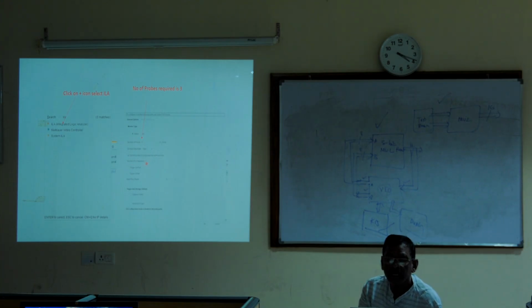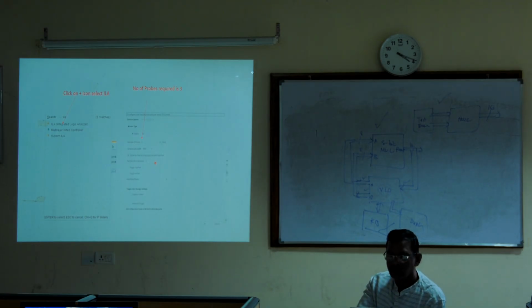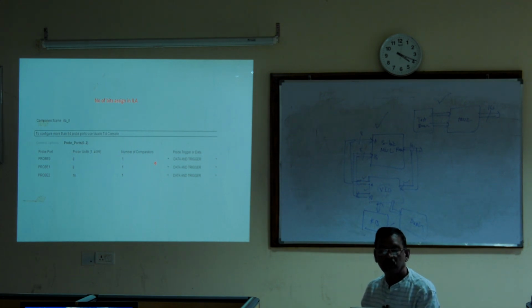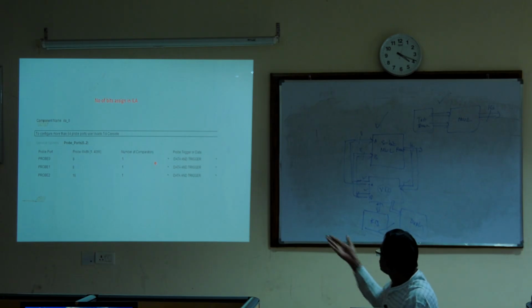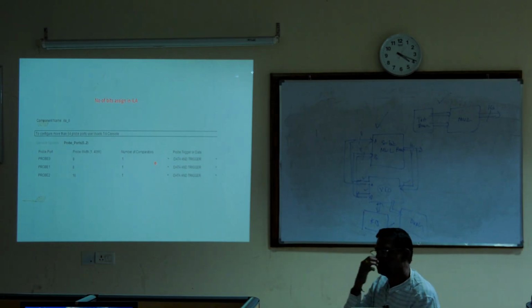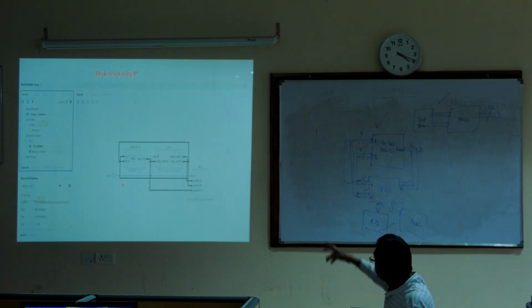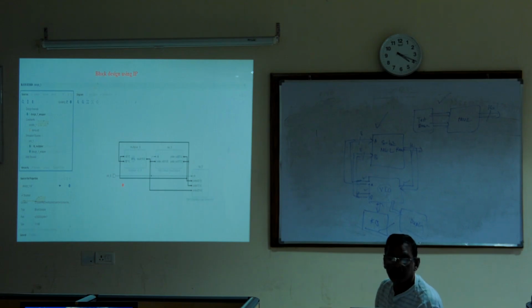Okay? And the same number of comparator outputs, then that's all. Then we just select the number of probes here, then the number of bits assigned in ILA. The number of bits is also the same, like 8 bits: 8-bit inputs and a 16-bit output. And the number of comparators is 1. So this is the final connection diagram. It's not properly visible here.